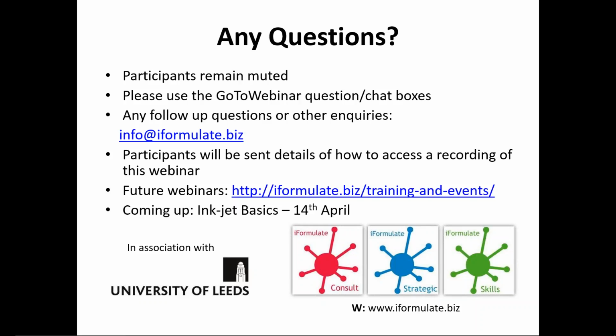And again, how much air depends on the process conditions. If you have a highly porous structure, then there's going to be a lot of air. If you dry it in a different set of conditions, you can have a nice solid particle, and the droplet actually shrinks as it dries, and as the water goes out. So you can actually form fairly low porous particles as well.